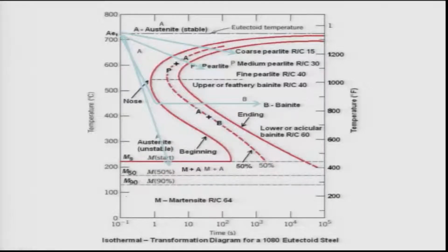If we quench to an oil bath at a temperature of 150 degrees Celsius, then it will lead to 50% to 60% martensite. And once it is quenched below 100 degrees Celsius, that is, suppose at room temperature 30 degrees Celsius, then almost 97% to 98% martensite will form.